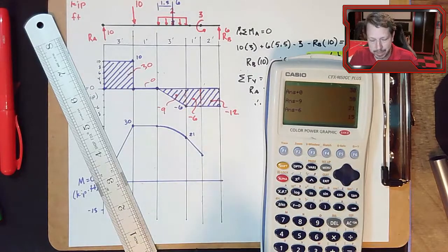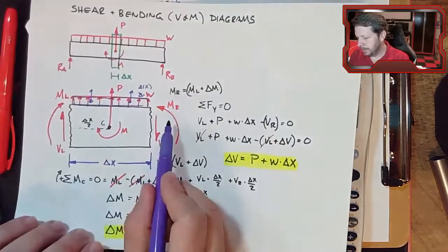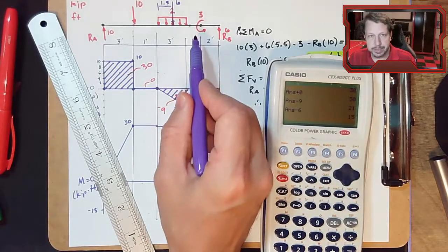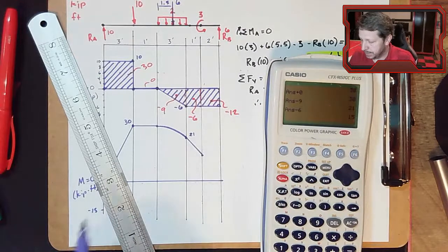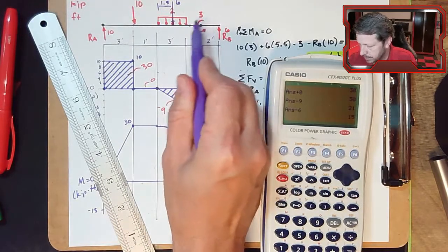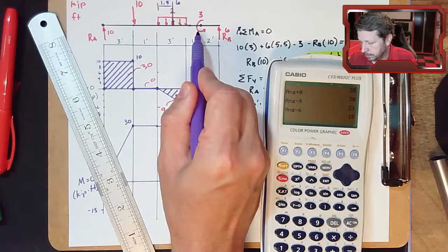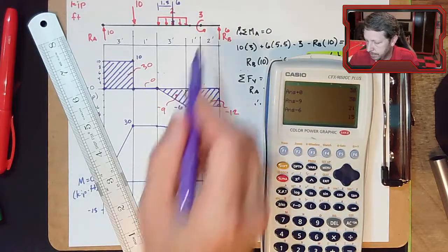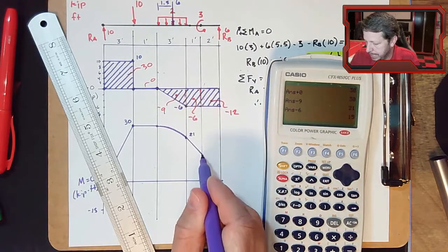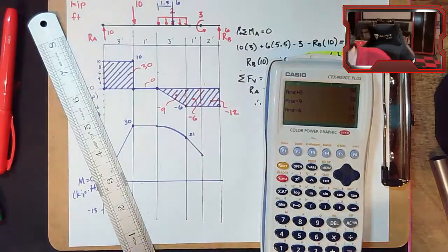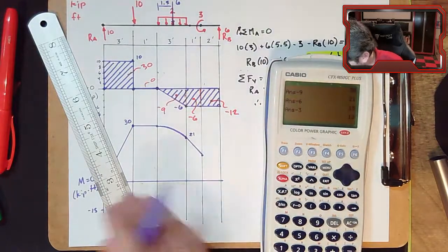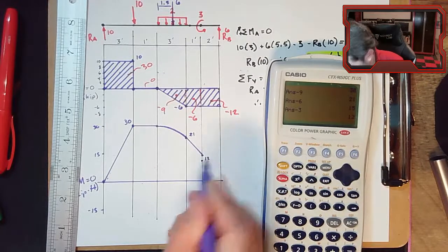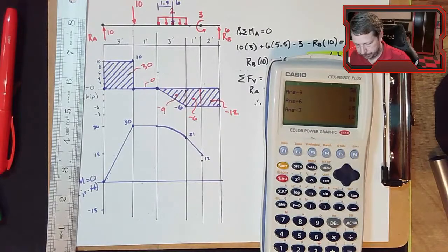You could do everything backwards, you know. You could put these opposite of what we've drawn, and you could say that counterclockwise is positive, but our convention that we're using is that external moments, concentrated moments on a beam, when we're drawing a shear and bending diagram, if they're counterclockwise, it's going to give us minus, in this case, 3. So minus 3. Brings us down to 12, which, I don't know, is somewhere in there. And it's a step change, so it goes straight down.